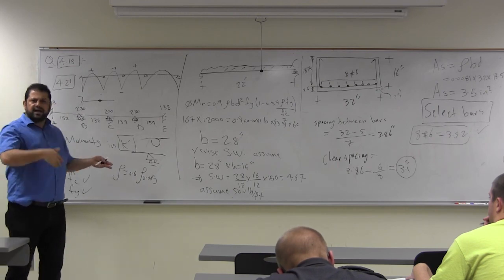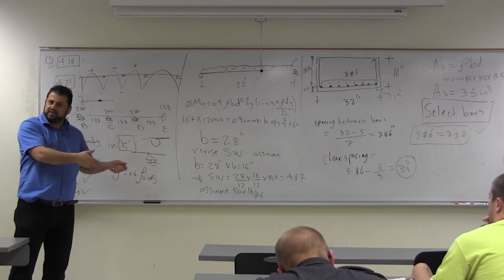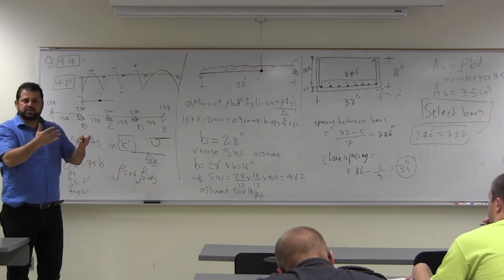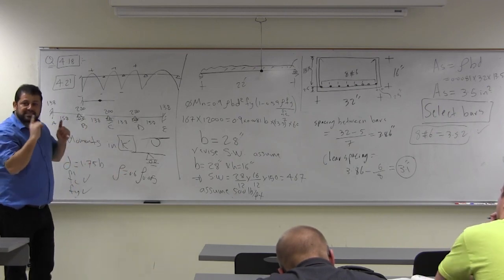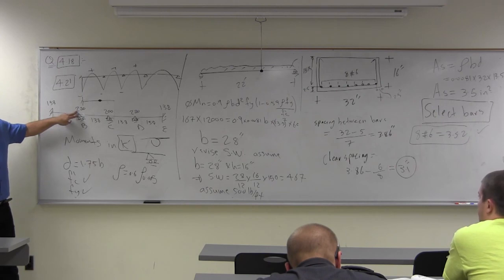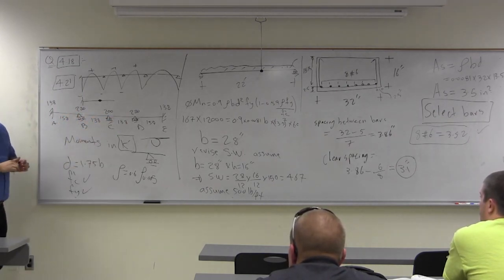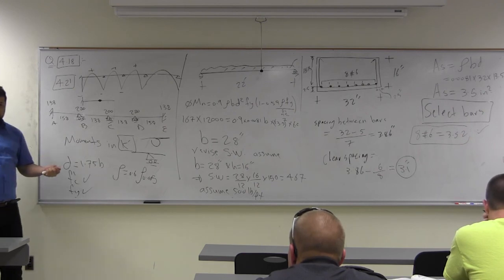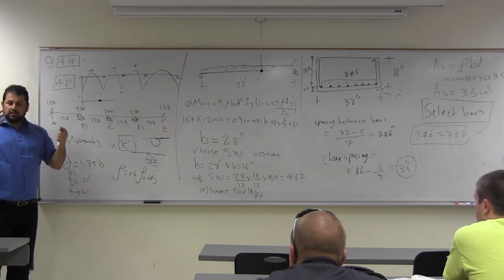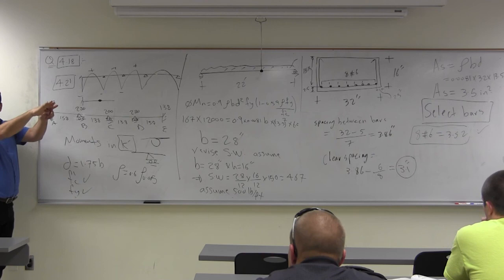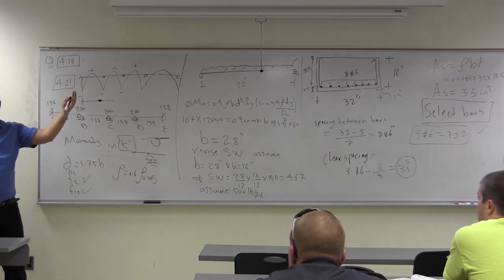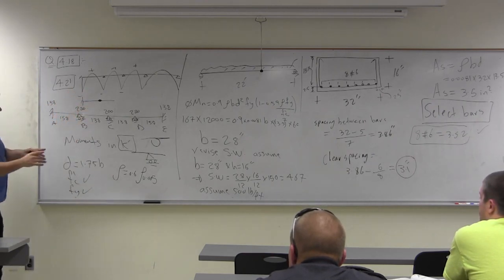B and D, and add a cover to one, say, assume 2.5 inch cover, you get B and H, right, for your section. You pick a steel for that moment, which is for this and that. You pick a steel, right? Then you go to this, and that steel must be top. Say like 5, number 7 or whatever. Then you use the same section.